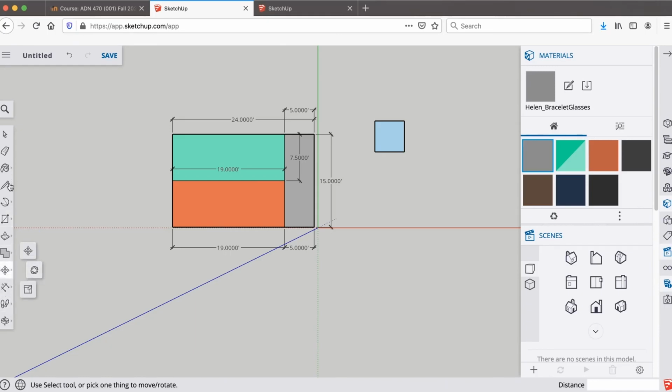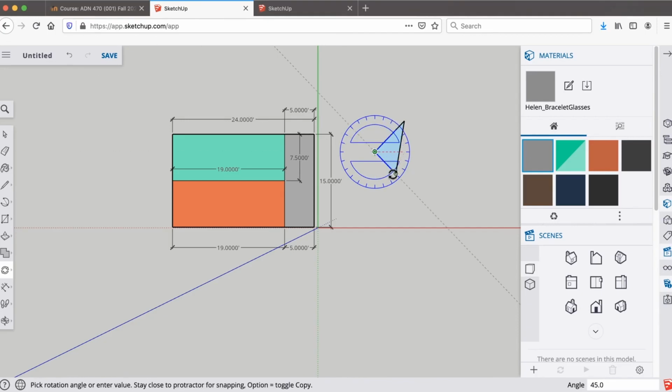Okay, sorry. This one has to do with arcs. My fault. Actually, you go here to the move tool. Duh. Move tool. Rotate. Makes sense. Okay, so when you get the little protractor here, you're going to click on the corner, right? You click on the other corner, and then that's going to rotate your line.